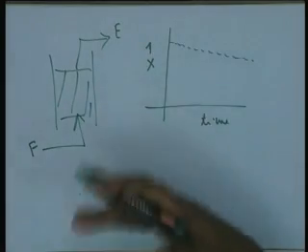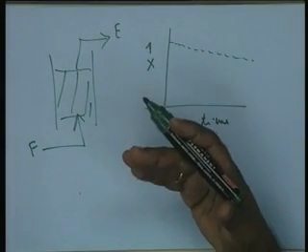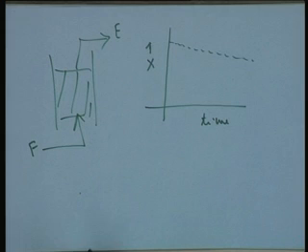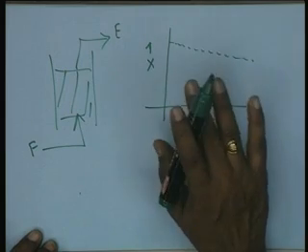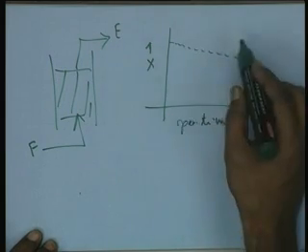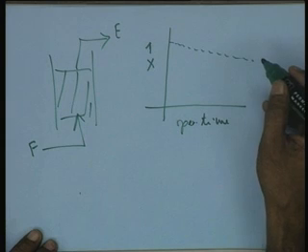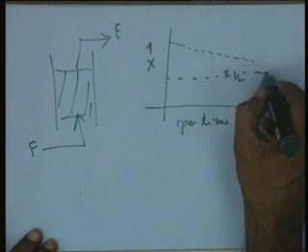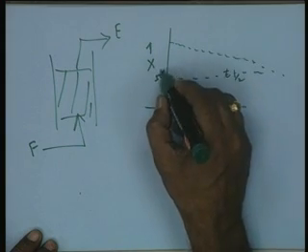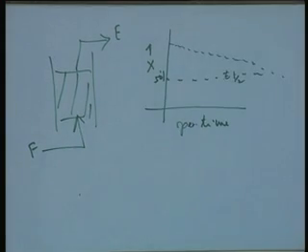As the enzyme activity is reduced, is lost, the fractional conversion keeping the residence time constant, over operational time, this is operational time, not the residence time. Residence time is constant here, it will go down, and if you consider it as a first order process, then the half life, that means the time it takes to reach 50% of the original value, is the half life.